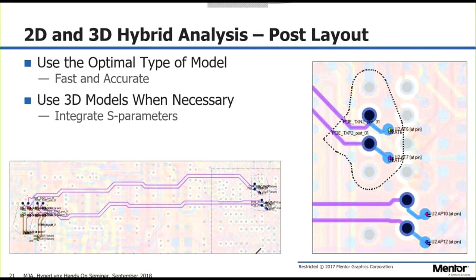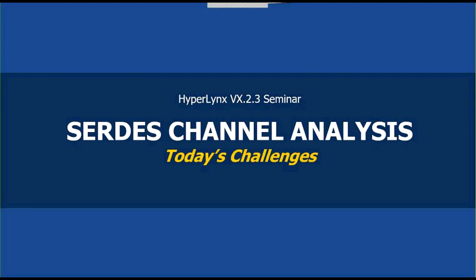So back to the view of the routed board. Again, we'll get the 3D models at these ends where we've got some odd critical stuff going on, but the traces in between, they can be handled by your classic 2D type transmission line modeling, and we're still getting really accurate results with that hybrid approach. So, you know, it's kind of an integration between the HyperLynx SI tools and these 3D field solvers to get the job done. All right, so moving on, we're going to talk a bit about the SerDes channel analysis problems